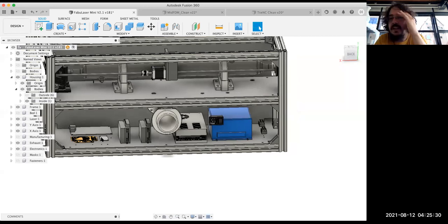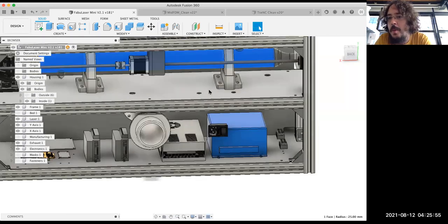But still, we discovered later that there are some quirks and some problems in the communication between the microcontroller and the laser power supply, because the laser power supply, guys, outputs 18 kilovolts and milliamps to drive this 40-watt laser tube. So this high voltage will create an immense noise inside your machine, and these aluminum composite panels can be also like capacitors somehow.